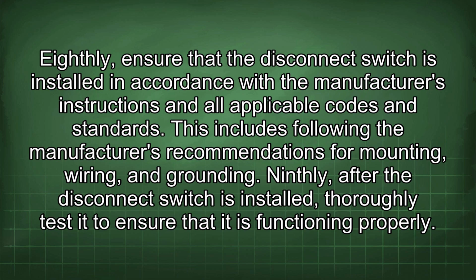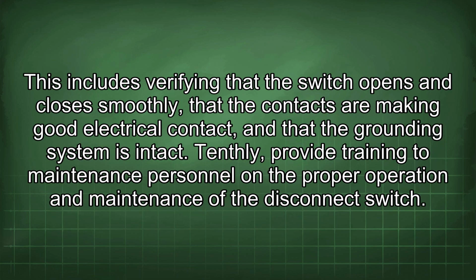Ninthly, after the disconnect switch is installed, it should be thoroughly tested to ensure that it is functioning properly. This includes verifying that the switch opens and closes smoothly, that the contacts are making good electrical contact, and that the grounding system is intact.